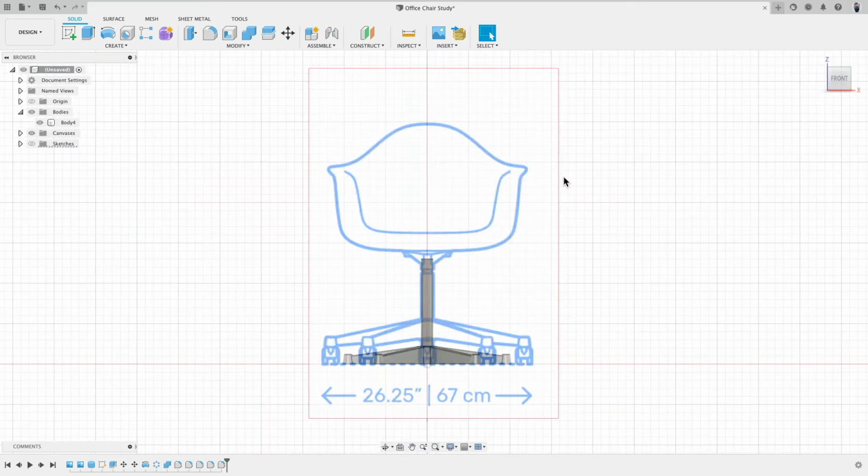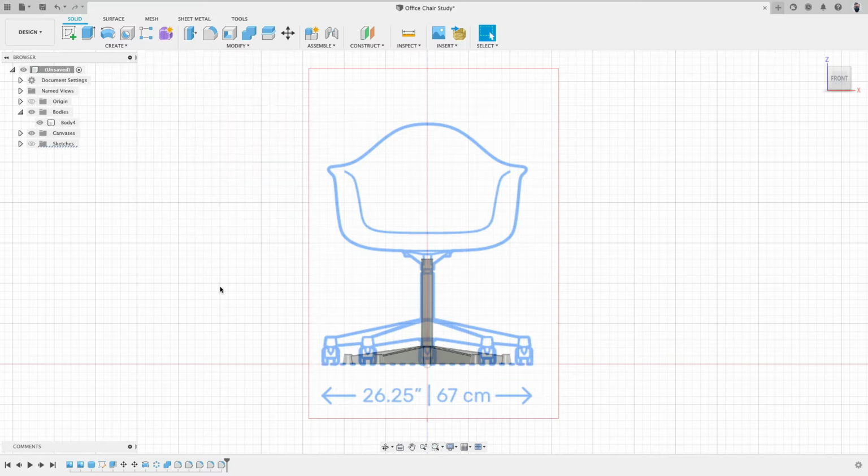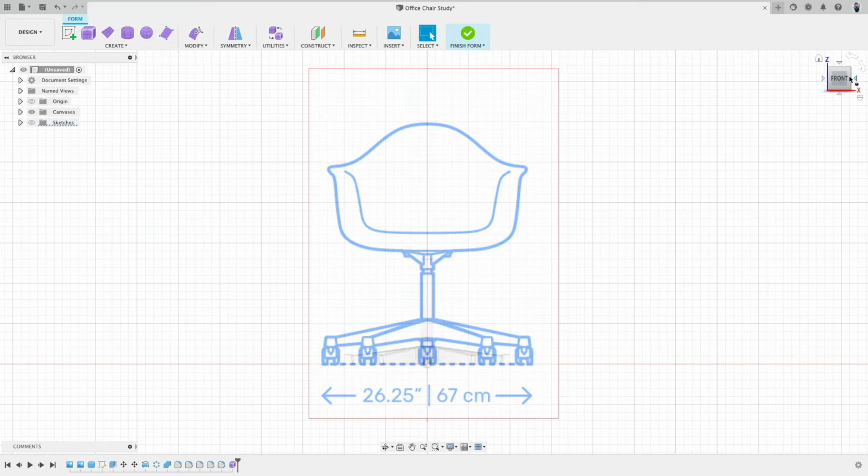So now we are ready to create our very quick ideation and studies for possible organic shell designs, which we could create via the create form command. Ideally in this mode, as a creative person, you want to turn off your brain. Our brain very often is our biggest enemy, and simply let yourself be guided by accidents, observations, and just the tools, and just work. Okay, so create form in the front view.